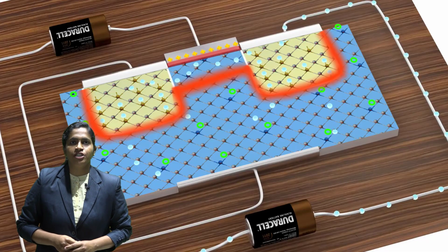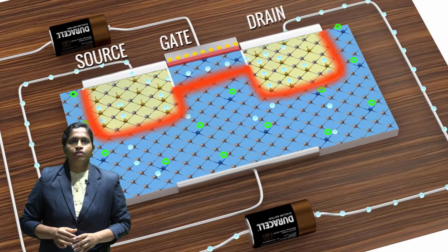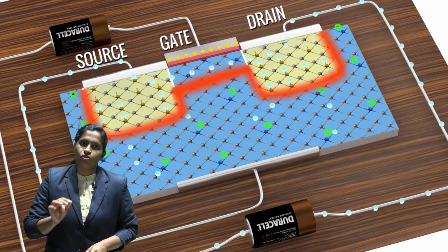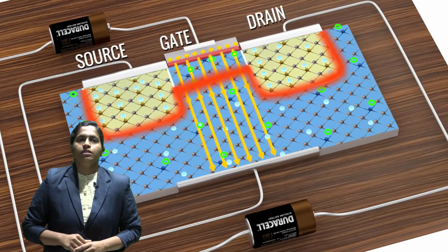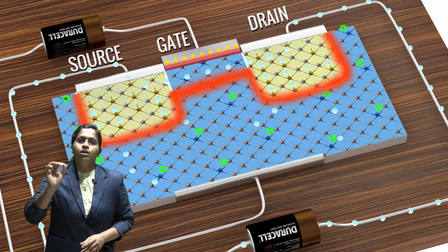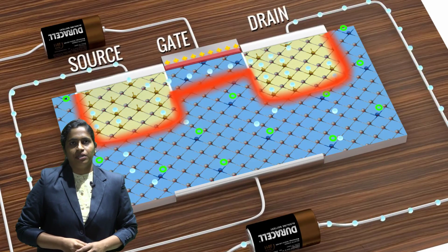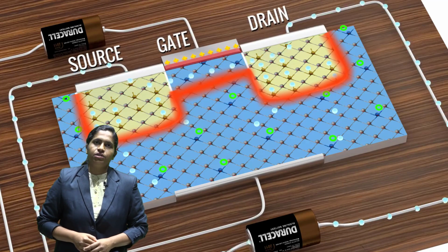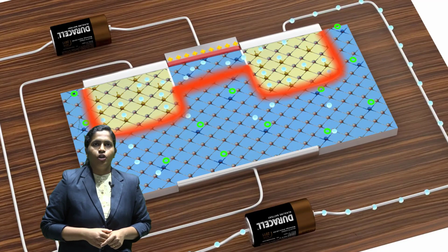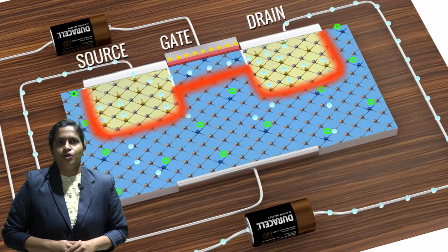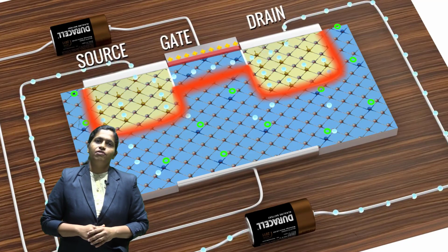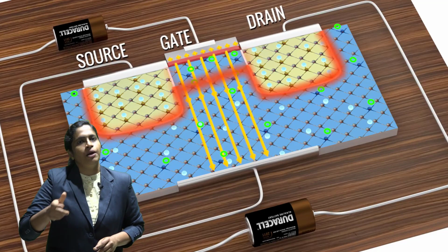Now understand the polarity conventions of the MOSFET. For an n-channel enhancement type MOSFET, the gate terminal is connected to positive and the source terminal to negative. For the voltage VDS, the drain is connected to the positive terminal and the source to the negative terminal. What about the substrate terminal? We always connect the source and substrate together, short circuiting them, so the voltage between source and substrate is 0. We mainly consider three terminals, gate, drain and source, and we make the gate terminal positive to turn on the MOSFET.